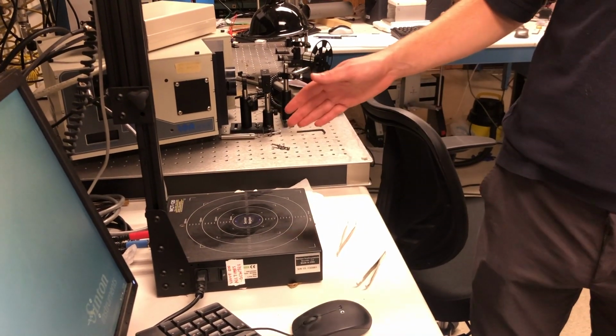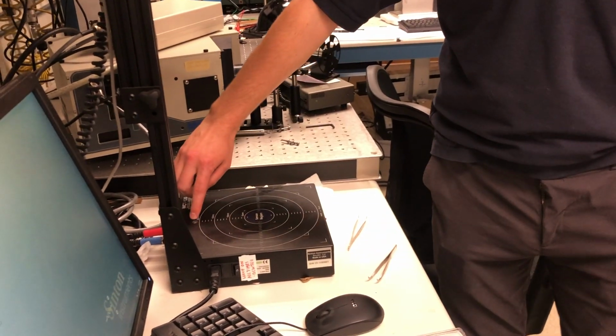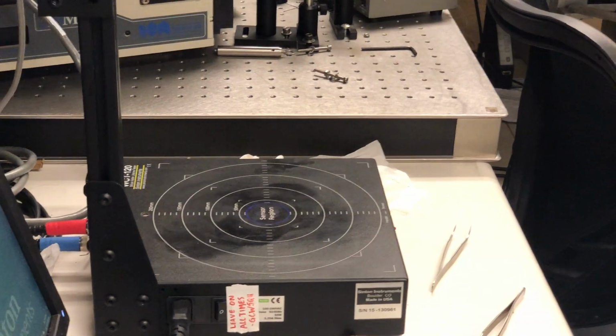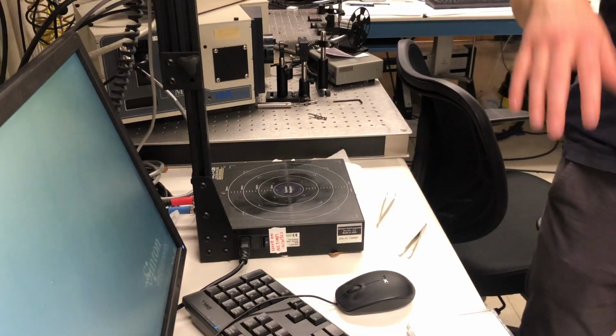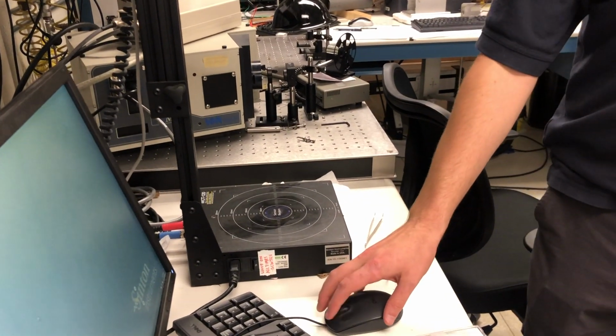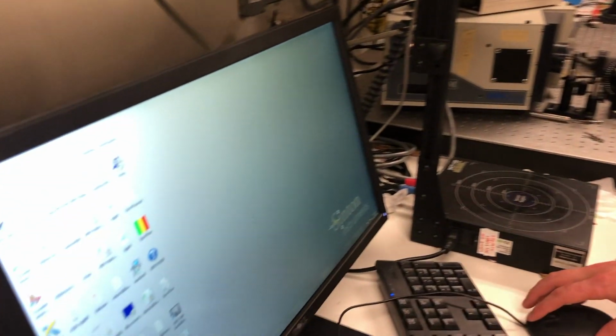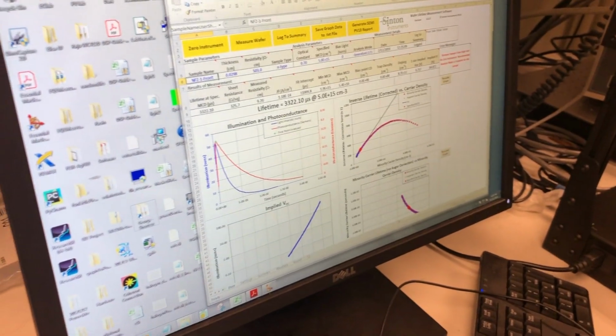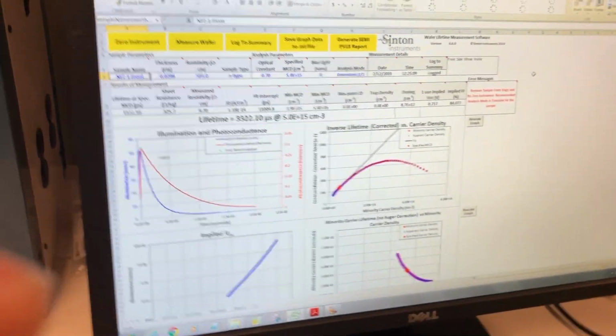And then it'll measure how quickly those electrons settle back down and recombine. The longer that takes, that's the lifetime. In the top here, there's also a little photo detector just to keep it calibrated in case this thing pulses inconsistently. So this one's also pretty well automated. I've already got a file set up for this cell. Here you can see what it gathers for you.